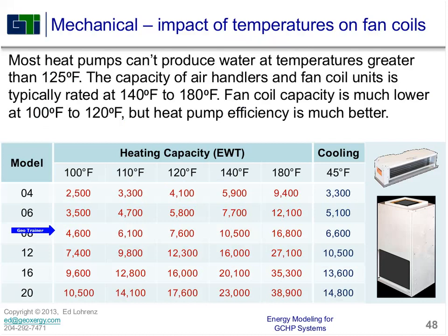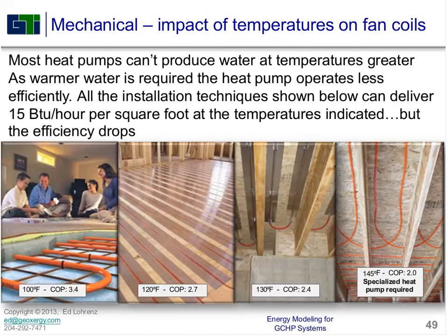You have to be aware of the implications of what you're doing when you're making these kinds of changes, and it will have an effect on how much water you have to supply, deliver to each of these fan coils, the piping size and things like that. But yeah, you have to look at the overall picture. But it can make a huge difference on how efficiently that system is going to operate.